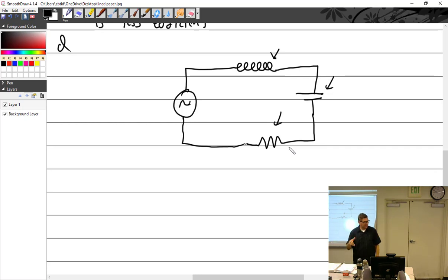Then it gets to a peak and then it kind of lets the current start to go. Then the field starts to collapse and it turns around and says, all right, all the electrons got to stop this way. Well, they don't necessarily stop, but it sure is a lot of resistance and it really slows them down going this way. And so that's why voltage goes and then the current goes. Current's always late to the party because the voltage is always trying to hold it up. Now check your ID, please. It's sitting at the door, won't let it through. So voltage is building up. It gets there first, so it causes the problem, and then the current can't get through. Everybody's with me on that one? Okay, hopefully that kind of explained it.